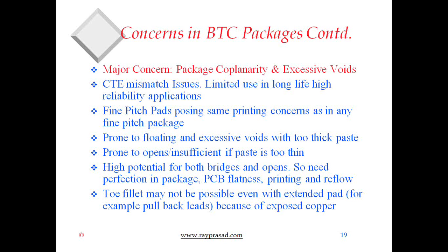And since you can only put on so much paste, as I suggested in the beginning, there is not much of a way to compensate for the flatness of the package. The only way is putting some extra paste, and then you'll end up having a lot of voids. And since there is no lead, there is a CTE mismatch issue. The package and the board do not have a similar coefficient of thermal expansion.